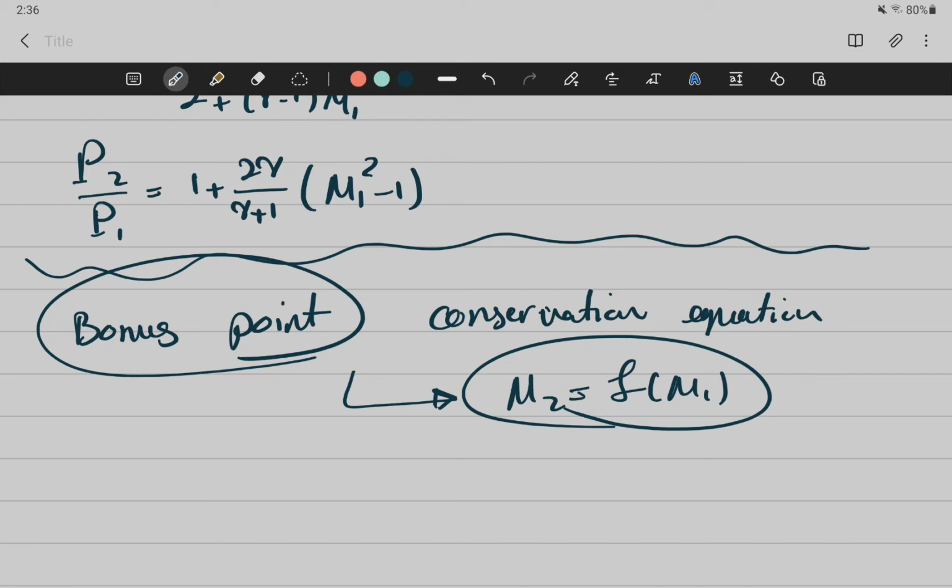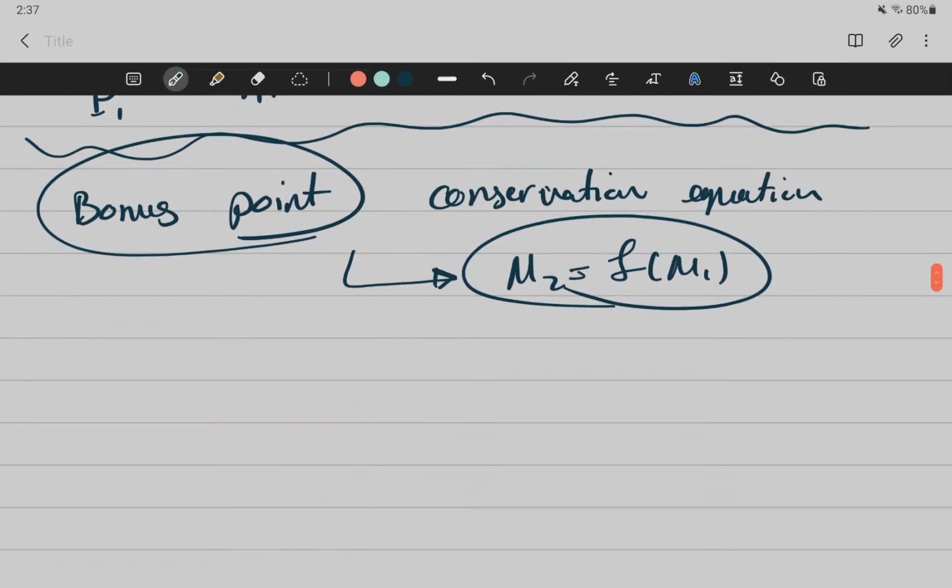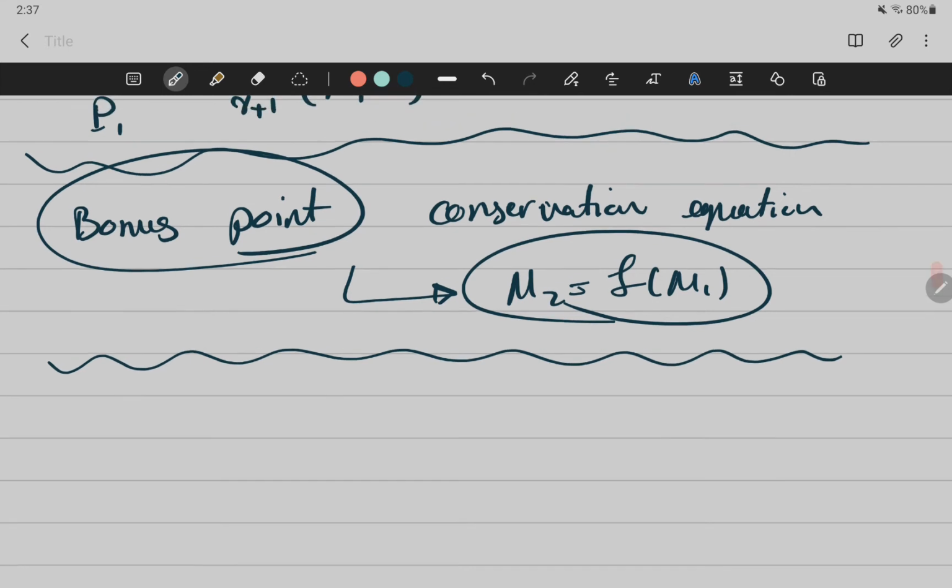How do we analyze it? Why do we have a normal shock wave? Actually, let's hear Igor's response. Why do we have a normal shock wave compared to other types of shock waves that we will talk about? When a blunt body passes through supersonic flow, that big cross-section area causes it to be a 0-degree wave. Okay, exactly. So essentially, as I said, this normal shock wave is a special case of shock waves, right?